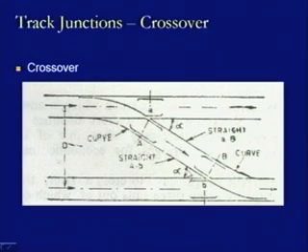So, this is the same angle alpha here as well as here, and here we have a crossing at this location, and we have another crossing at the bottom also, at this location. So, we have a pair of wing rails here, a pair of wing rails here, a check rail on this side, a check rail on this side, and check rails here also and here. So, two pairs of check rails are there. Then there is one point of switch here and one point of switch here. So, two pairs of points and switches will also be provided in this case. So, these are the constituent assemblies for any crossover.